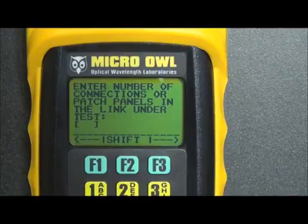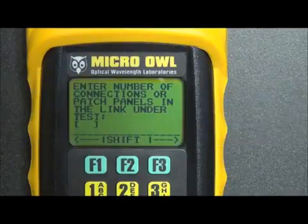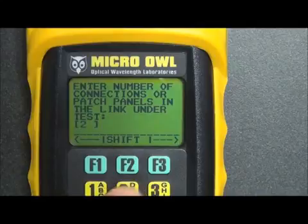Now, we are asked to enter the number of connections in the link under test. A connection is simply a patch panel, or it could be a wall plate or another mating sleeve. What we have to do is count how many of these connections are in our link. Typically, this will be 2 because you'll have a patch panel at either end of the link. So let's assume that we're testing a typical link. We'll press 2 and then hit Done.